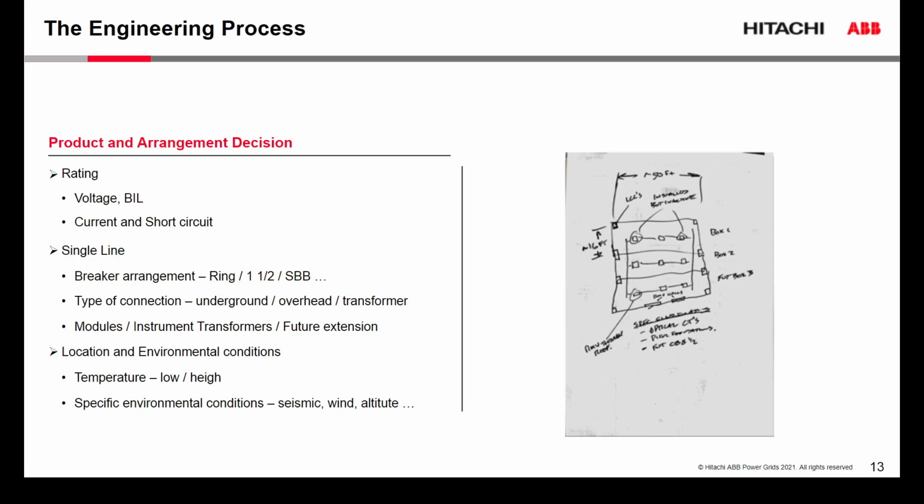So we would, for example, do overload calculations, SF6 calculations, to see that the technology will fulfill the requirements of its specific requirement. And are there other specific environmental conditions, seismic, for example, wind loads, high altitude, that are items which make sense to have in the specification and to review. The more such information is available, the more accurate the outcome of the drawing, of the technical